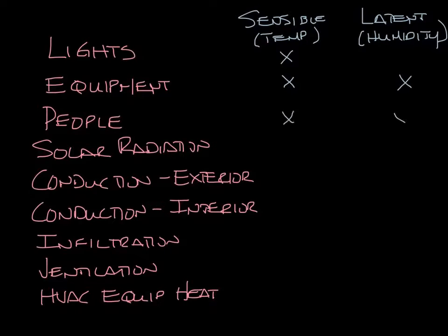People are both a sensible and latent load. Solar radiation is sensible only. Conduction, both of these are sensible. Infiltration will be sensible and latent. Ventilation will be sensible and latent, and the heat from the HVAC equipment will be just sensible.